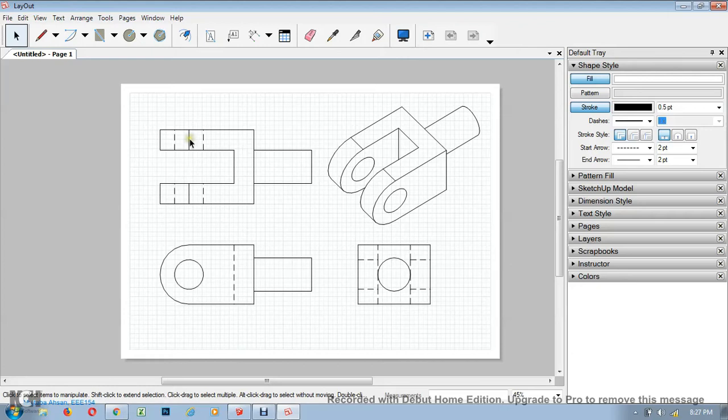I would also select this line and drag it here because this was exactly on top, so this goes through the center, and drag it here to make it smaller, and drag this line somewhere here because these are our center lines. Now you see I need more center lines here and here as well as here, so these I cannot get from this drawing, so I'll just have to draw them.